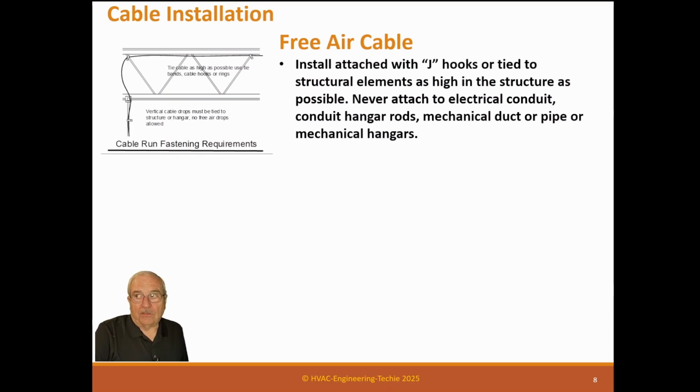Never attach to electrical conduit hanger rods, mechanical duct, or pipe, or mechanical hangers. And the reason is because your wire will get destroyed, because there's a lot of things, and some of those things move, like pipe. They actually move.